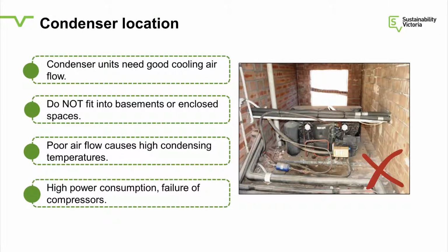Condensers, as I'll take you back to that little diagram I showed you right at the beginning. Condensers need air to cool. They need lots of air. If they don't have air, the temperature will go up and the refrigeration system will use more power. So condensing units need good cooling air. Do not fit them into basements or enclosed spaces.